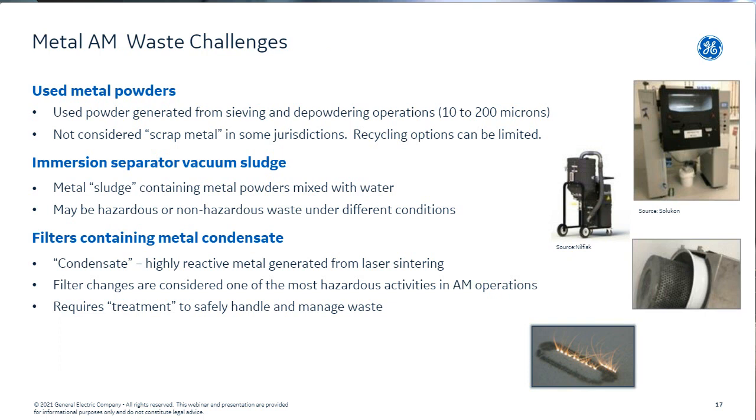So when it comes to your powders and metal additive manufacturing overall, what specific challenges do we have in addition to what I've already told you? It's really about the used metal powders. As I already said, when you reuse and sieve it, you can come to a point where you don't have the specific criteria anymore, or even your application doesn't allow you to reuse the powder. As an example, if you're printing equipment for aerospace applications, etc.